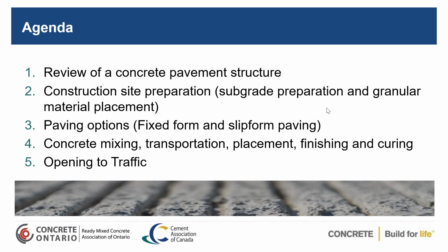Next, we're going to get into the different paving options when it comes to municipal concrete pavements. So there's fixed form and slipform paving. We'll show you some advantages and disadvantages of using each one. Then we'll get into concrete mixing, transportation, placement, finishing, curing, and jointing as well. And finally, we'll finish off with some requirements from OPSS in terms of opening the pavement to traffic.